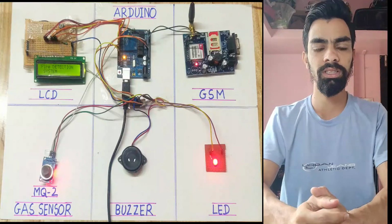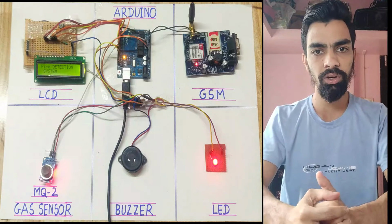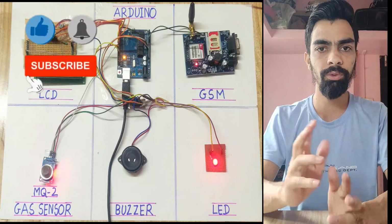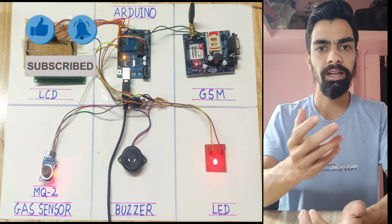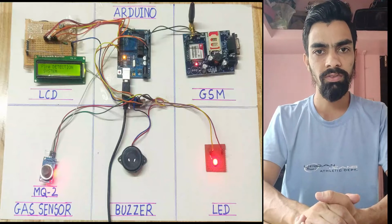Hello friend, in today's session we will learn how we can design a fire detection system by using the Arduino software and Arduino hardware. In this project we will use an MQ2 sensor which detects the fire, and there is an LCD also and a SIM900A to send the message once the fire is detected.